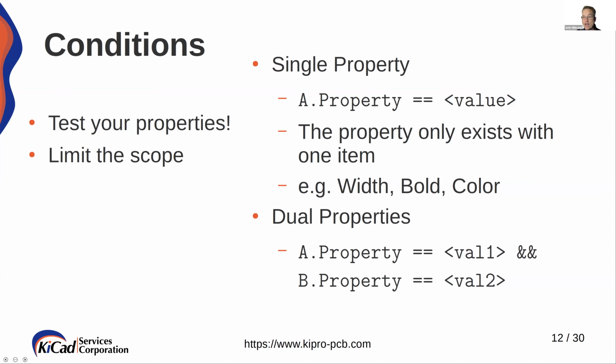Maybe you have a square pad, and you want to provide a little extra clearance to the copper to make sure that you're not exposing the copper with a mask that you would not otherwise need to provide for a circular pad because you have some rounding on the corners. Each of these properties of an element can be included in the rule in order to limit where the condition applies.